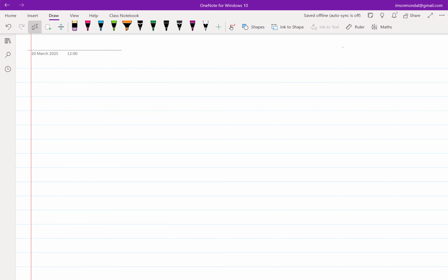So what people figured was, if we model currents and voltages in terms of signal waves, then we have a way of mitigating the reflection. The way of mitigating the reflection is to ensure that there is always a matched termination at the source side and at the load side. If there is a matched termination at both sides, there is no reflection, and the problems that come because of reflections will not be there. So a new set of parameters were envisaged, called scattering parameters, or S parameters.